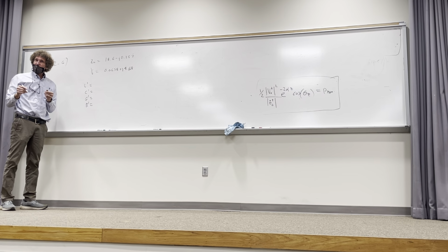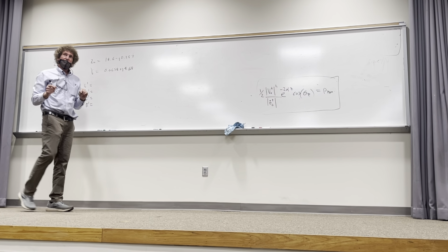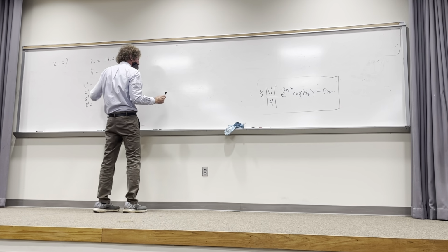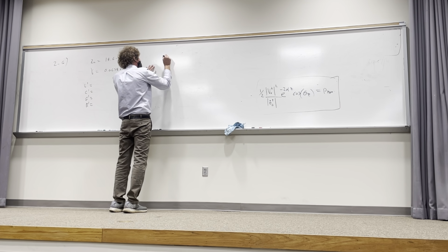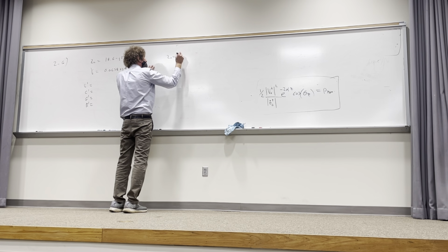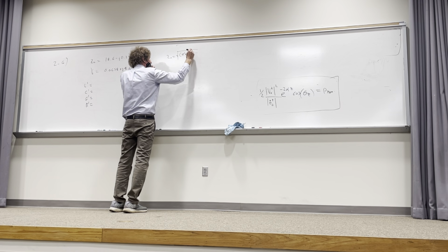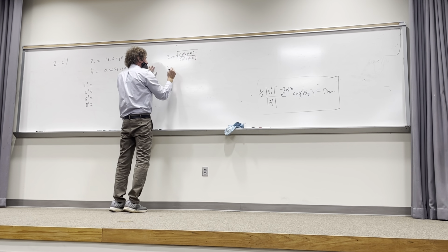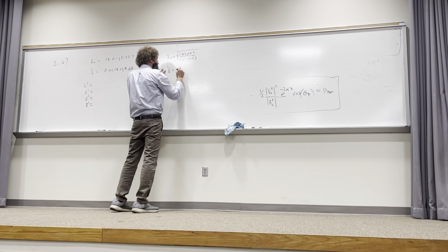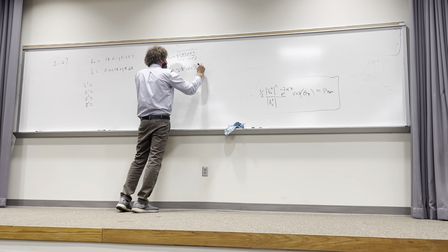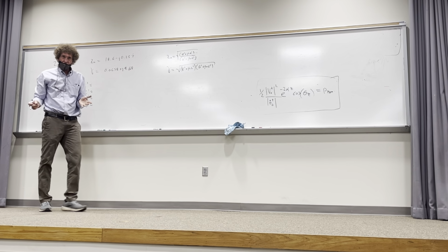The way you get this is always think of how these things have been defined in terms of what they're asking for. So Z naught, the characteristic impedance, was equal to the square root of (R prime plus j omega L prime) over (G prime plus j omega C prime), right? And gamma was equal to the square root of (R prime plus j omega L prime) times (G prime plus j omega C prime). Can you all follow me on that? I'm just showing you the thought.